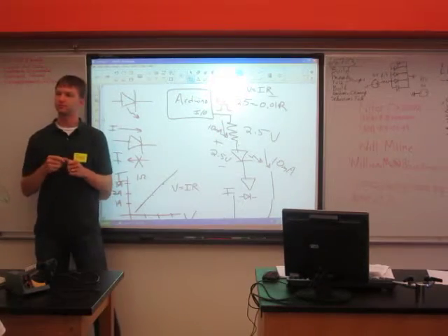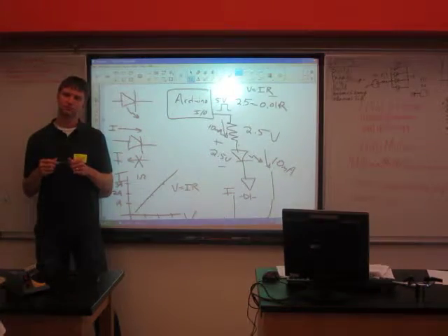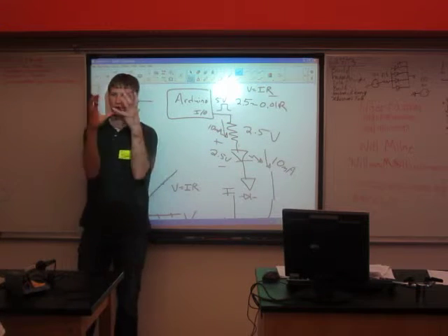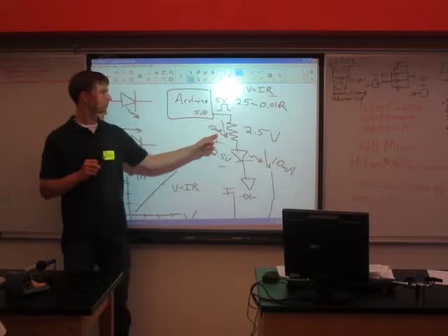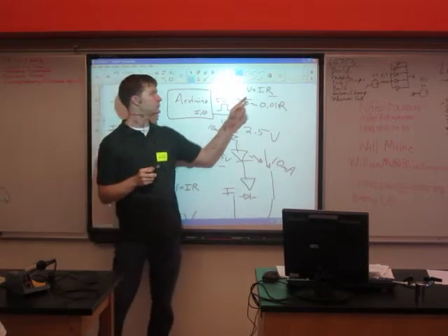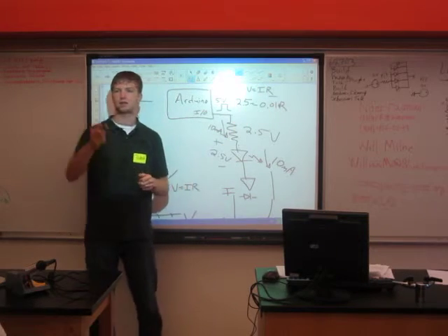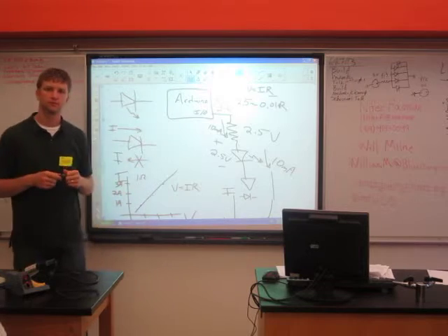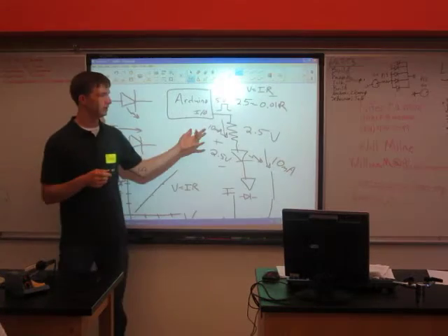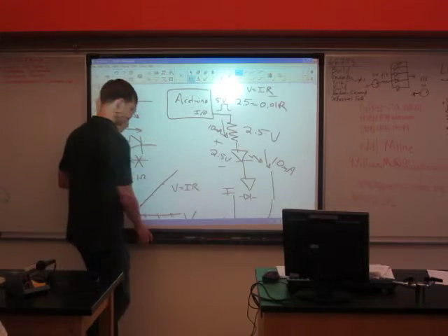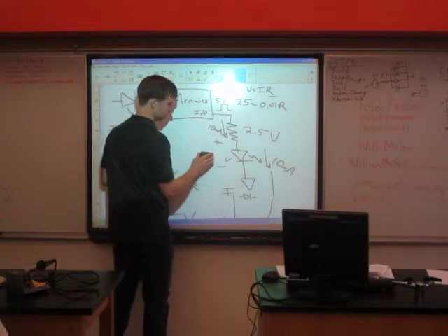Because that's the voltage drop that you want across the resistor. Boom. So you're talking about really one component here, this resistor. You want 2.5 to match 10 milliamps using whatever value it takes to make that happen. Is 2.5 the drop, or is 2.5 the amount that you need for the LED? In this case it's both, but if you were to do this equation. Right. So let's just change this up a little bit to make this more clear.